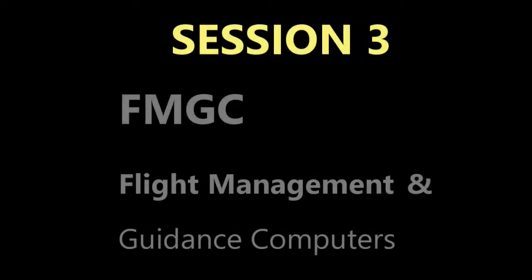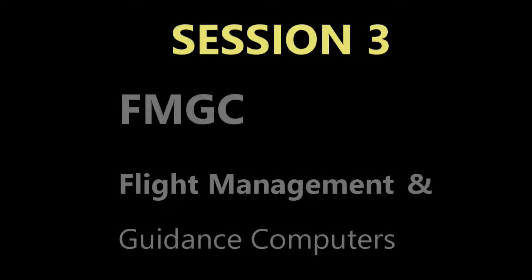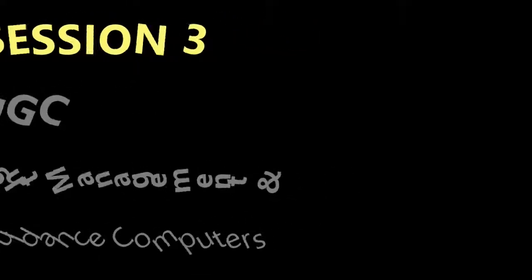So those are your 4 buttons across there on the panel on the FCU, and then you also have the autopilot 1 and 2. So autopilot 1 and 2 are located just above the auto thrust engagement push button. Okay, and when it's active, it's going to show 3 horizontal dashes above the abbreviation on the push button. So if you don't see it, it's not active. If you see those 3 lines that are green, then that means it's active. Okay, it's been activated.